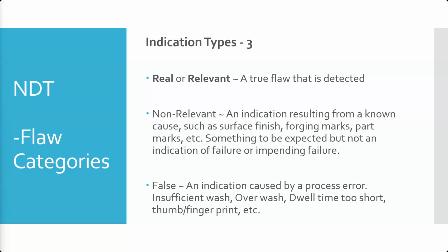So we found a crack that's real or relevant. It doesn't always mean the part's not serviceable. You have to look at limits. The part manufacturer or the part overhaul, whoever has responsibility for the part or the aircraft, they're going to give you those limits. And then you, as the technician performing it, are going to make that determination. And that's why we're going to have to document what we find.